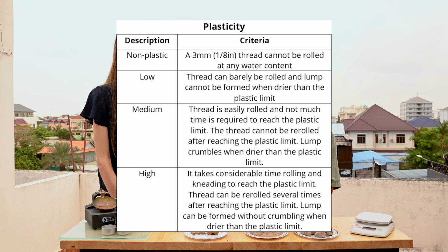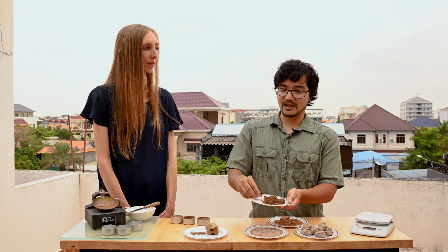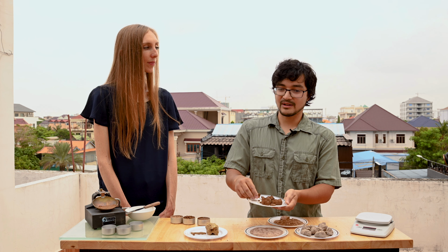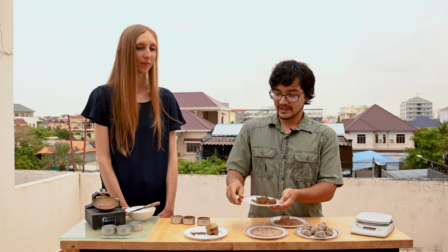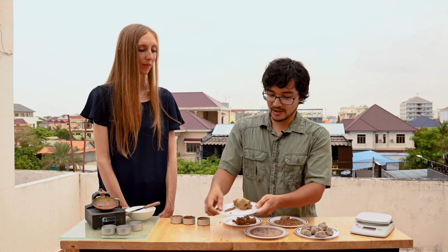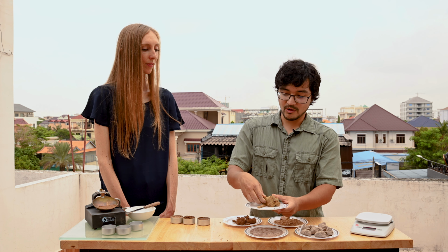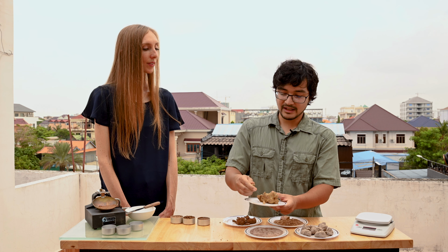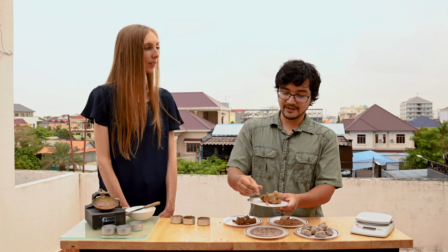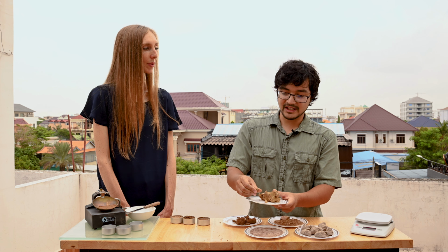Low plasticity fine-grained soil is a soil that can only undergo a little bit of stress or strain without beginning to crack. And a high plasticity soil is one that you can roll into a thin thread. It's a soil that can undergo a lot of strain when applied stress.